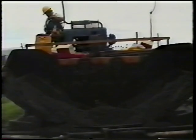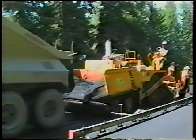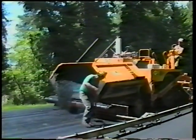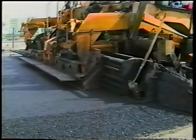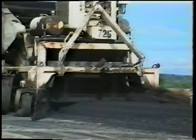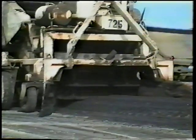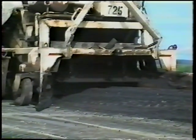Okay, now let's look at the paver or laydown machine. There are many types, but all consist of a tractor and a screed. The tractor, of course, provides the power and includes a hopper where the mix is deposited. The screed's functions are to smooth and partially compact the mix. When belly dump trucks are used, a pickup machine is attached to the front of the tractor. Let's take a closer look at each component, beginning with the pickup machine.